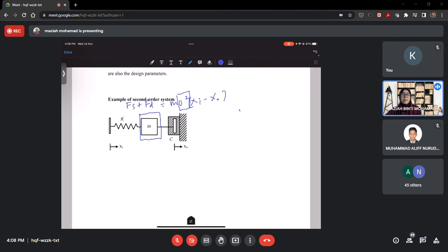When we derived the time response equation, d square is the second differentiation term. If we convert into Laplace, d square becomes s square, which will be at the denominator of the transfer function. That's why the transfer function becomes a second order system, as the highest order of the denominator is 2.